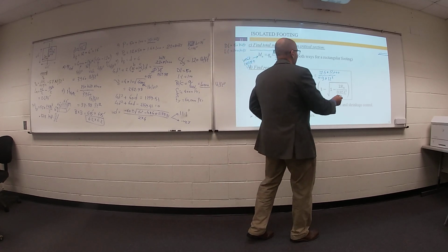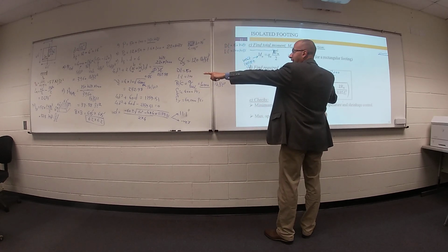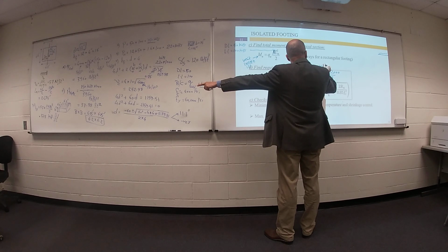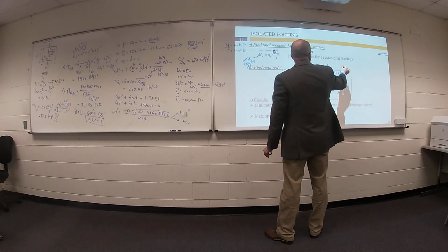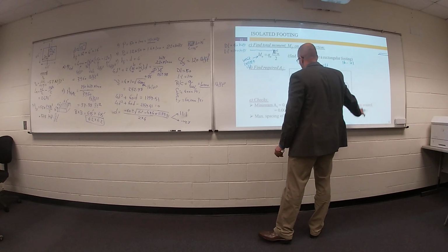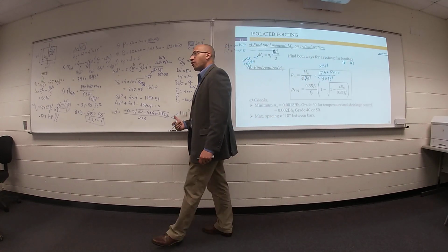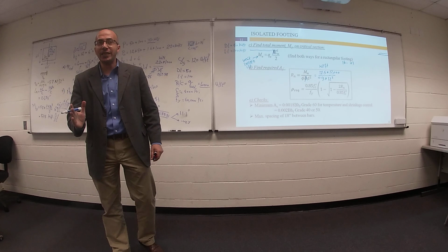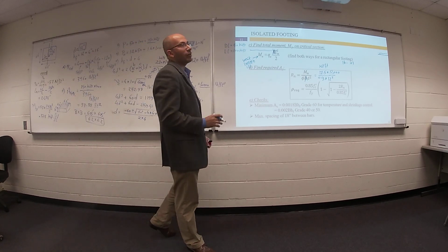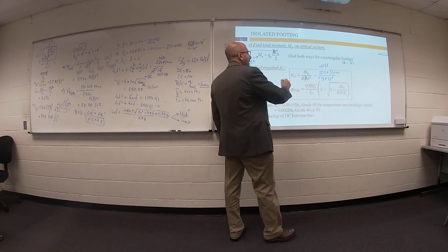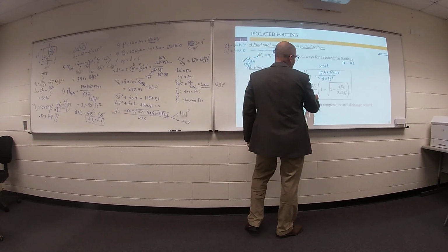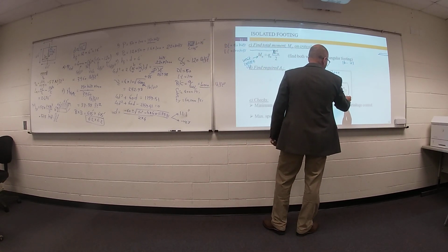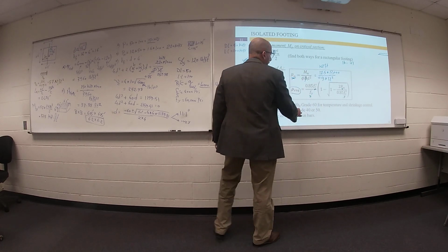Good question. Your 17.5, go back to your unit, it's kip-foot. I would like to convert everything to pound and inch. From kip to pound, 1,000. From feet to inch, 12. So we have 12,000. Go ahead and get your Rn. Once you get Rn, put F yield, Fc prime, and Rn to get your rho required.